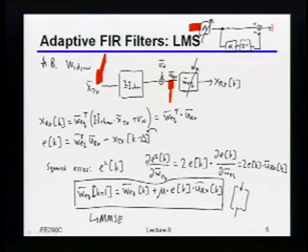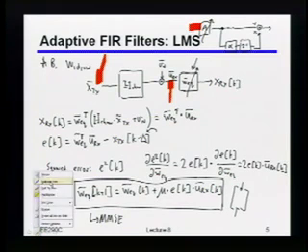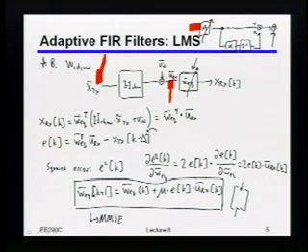It's not too bad, but again, I'm really lazy, okay? So I don't want to add any extra variable stuff in my high-speed signal path. But there's a way to do something very similar to what you just said, just flipping it on its head. In what you just said, you had a fixed reference voltage over here, and then you tuned that gain so that everything matched that reference voltage.